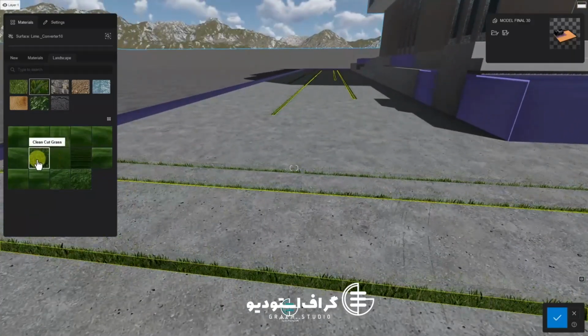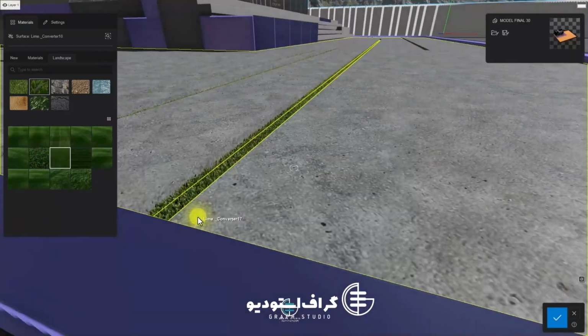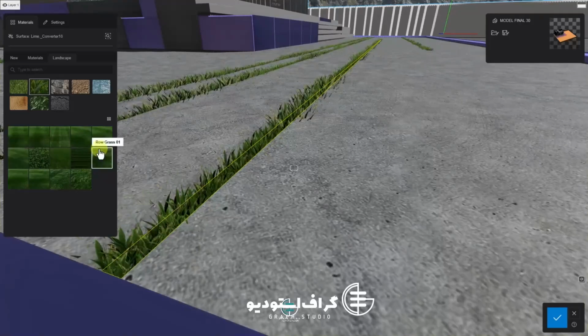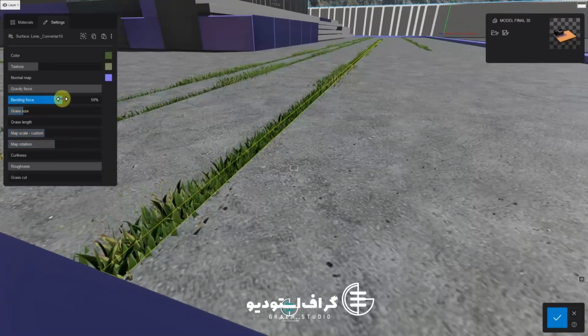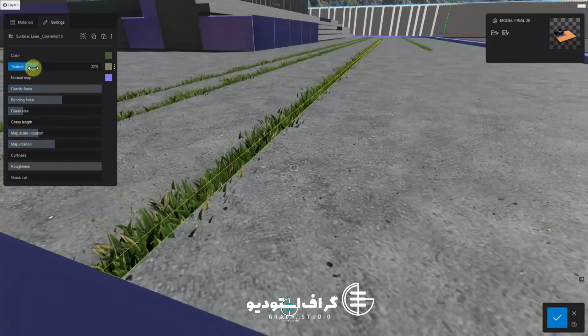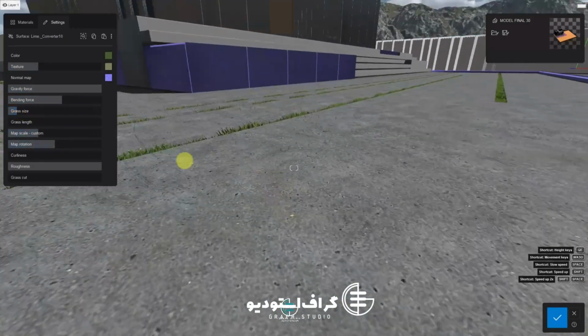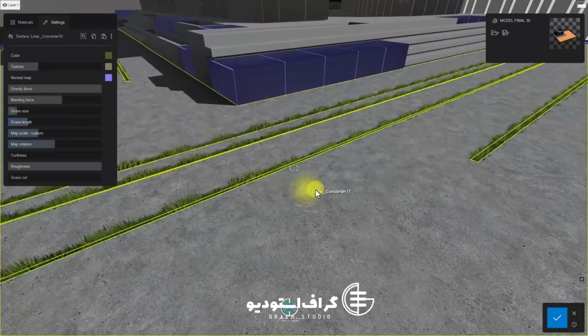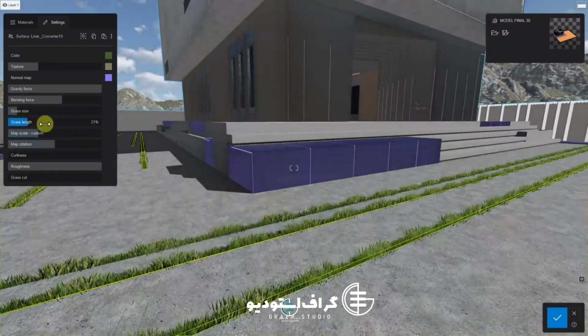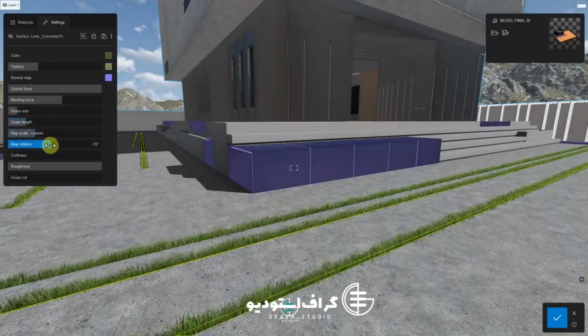Well, now that our editing is finished, we must repeat the same process. Guys, Control plus select the whole scene, check that you've selected everything. File, Export, Export Selected. You don't need to overwrite the old file. I'll name it, say, 40, because we need to remodel and select the new file. Okay, done. I return to Lumion.